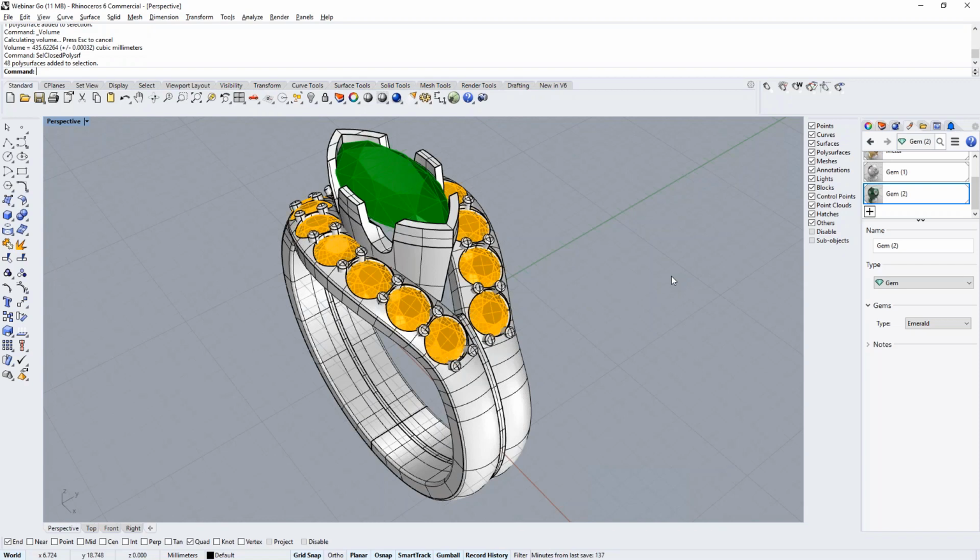Now, as far as I know, almost every resin printer, both the DLP and the SLA and the new ones, the LED printers, will print overlapping solids. They won't print something that's not closed, but you can have solids that are overlapping, like in this case, and it will see it, slice it, and print it just fine. Great. Okay.